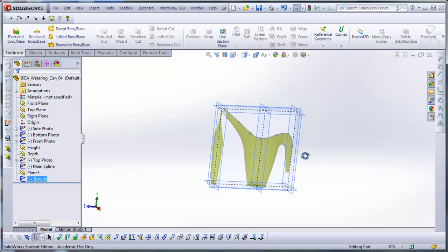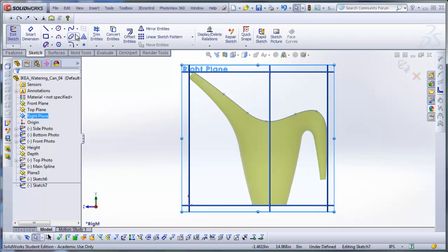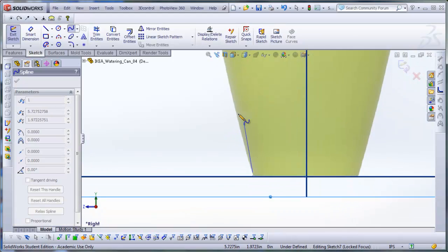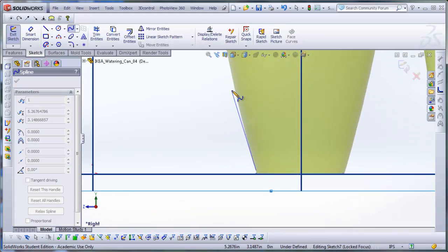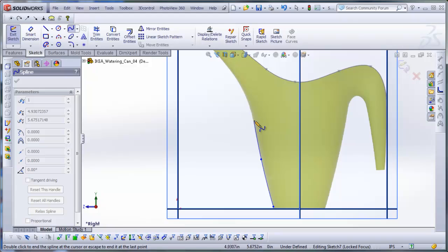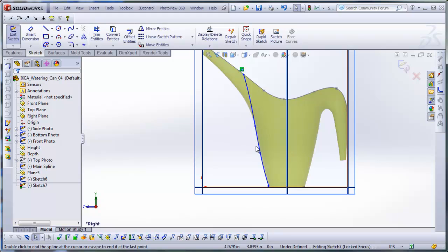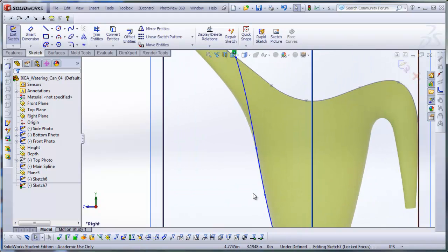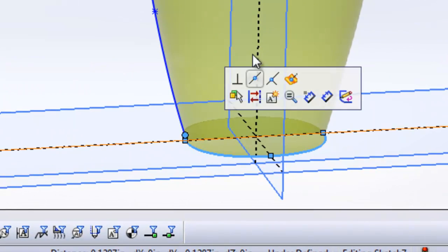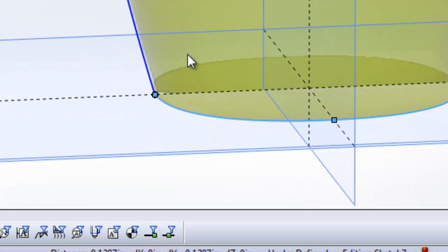And then I'm going to again draw on the right plane. Let's sketch, and I'll draw some splines, and I'll get just close. I'll use SolidWorks to pierce that later. So I'm just gonna get close here. There's a little bit of an S inflection, so I'm using more spline points than just 2, because it kind of has a little bit of an S shape. So I'll go back here and I'll pierce these two together by holding control. Endpoint always pierces, always point and curve.